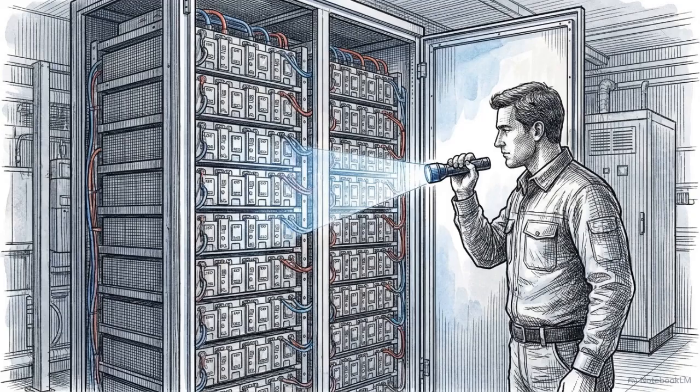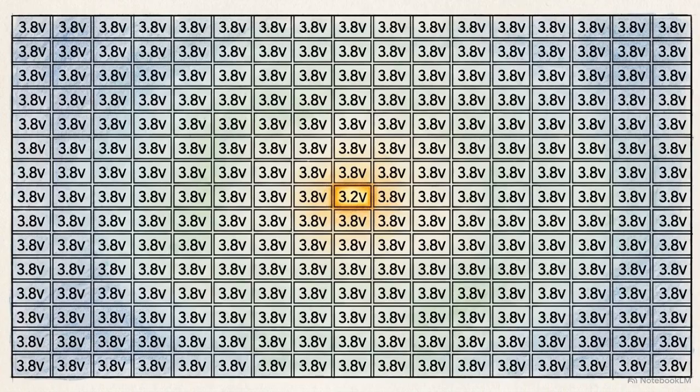On a shift-level basis, operators perform a deep audit of the battery system. This involves scanning individual rack and cell tables for localized temperature spikes or voltage imbalances that are not visible in the top-level state of charge metrics.